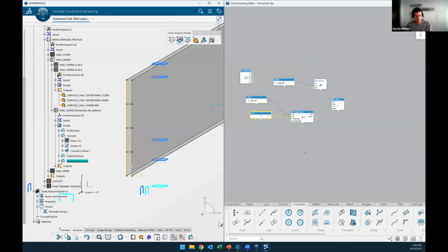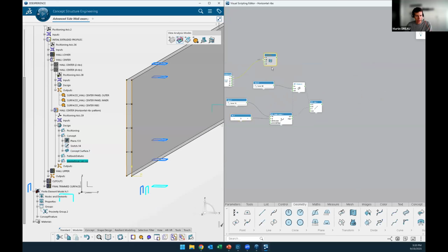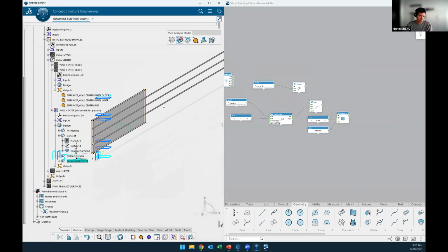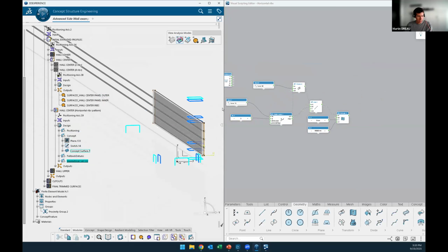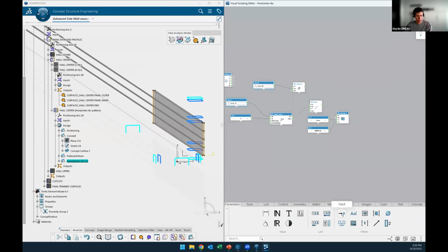And now, as I said, to get the rib surfaces, I will extrude this line in the right direction, YZ, with the right length. So here, I'll use a very large length, and then I will split those extrudes using my architecture planes. So I need to input those architecture planes.